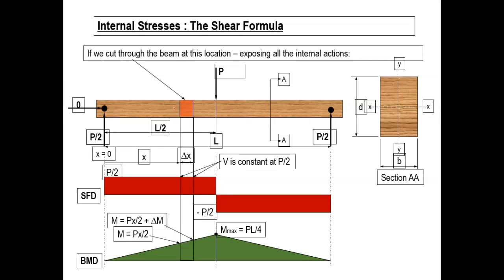Internal stresses on this side and internal stresses on that side. They are not the same, because I told you that the normal stress is a function of x, because the bending moment changes. When you are here, the bending moment is that. When you are there, the bending moment is that. They are not equal. So if I try to show that internal stress on the left and right hand side of my coupon, unfortunately, those variations are not uniform.